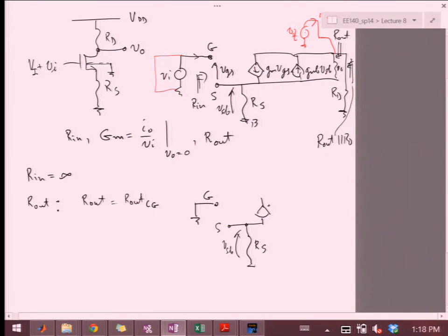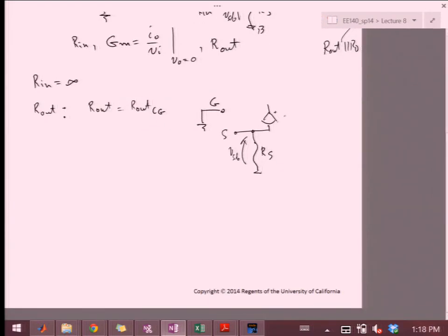Right? So then I'll just flip the sign of this current to go up and have gm times VSB here. Then both of these add up, and I get one current source that is (gm plus gmb) VSB. And that into r0 gives me this Thevenin voltage,